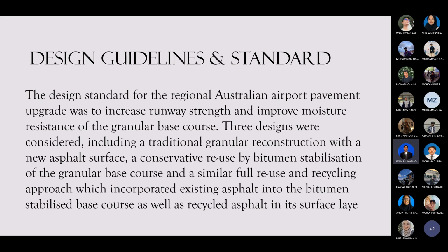Next is design guideline as standard. This design was to increase runway strength and improve moisture resistance of the granular base course. Three designs were considered, which is traditional granular reconstruction, next is conservative reuse by bitumen stabilization of the granular base course, and full reuse and recycling approach, which incorporates existing asphalt into the bitumen stabilized base course as well as recycled asphalt in its surface.